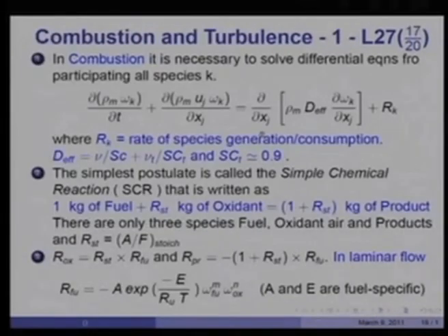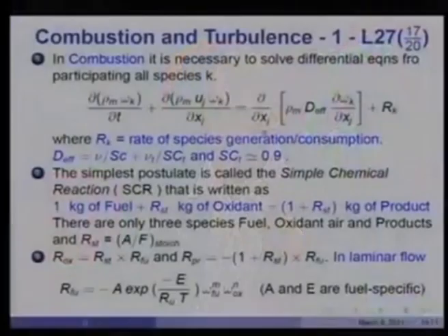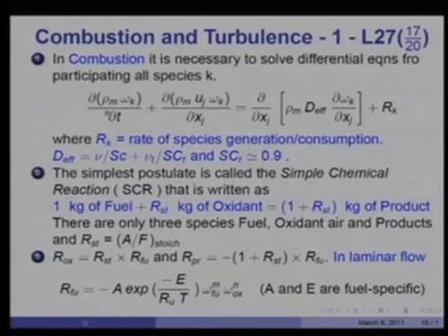Lastly, I turn to the topic of interaction between combustion and turbulence. So, in combustion, it is necessary to solve for reacting species and product species that are postulated in a reaction mechanism, and the equation reads like this: for each species k, the mass fraction omega_k, convection of that equals diffusion of that plus the rate of production or destruction of that depending on the sign of R_k.